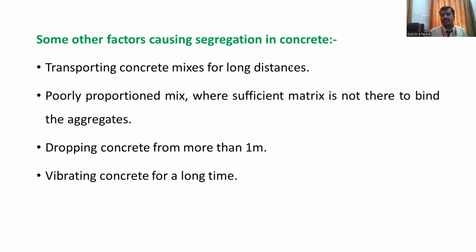Some factors which are causing segregation, we will discuss which factors will cause the segregation. Transportation of the concrete mix for a long distance. If you are going to transport your concrete for a long distance, it may happen that there will be segregation. Or a poorly proportioned mix, that is you have not prepared the mix as per the design that you are given. Then dropping of the concrete from 1 meter height and vibrating the concrete, that is over compaction, for a long time. These are a few factors which will affect segregation.